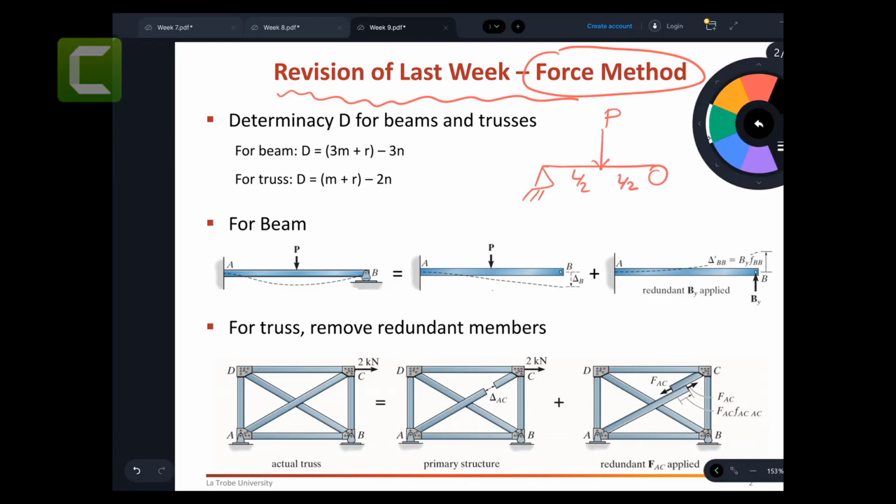In this kind of case, you typically have three reaction forces required to calculate. Well, it is easy because you have sum of the moment equal to 0, sum of the force in the x direction equal to 0, sum of the force in the y direction equal to 0. So these structures need to be in equilibrium, meaning that this structure is not moving in space. All the forces and all the moments coming on that particular beam are 0. And using those conditions, we can calculate those three unknown reaction forces.